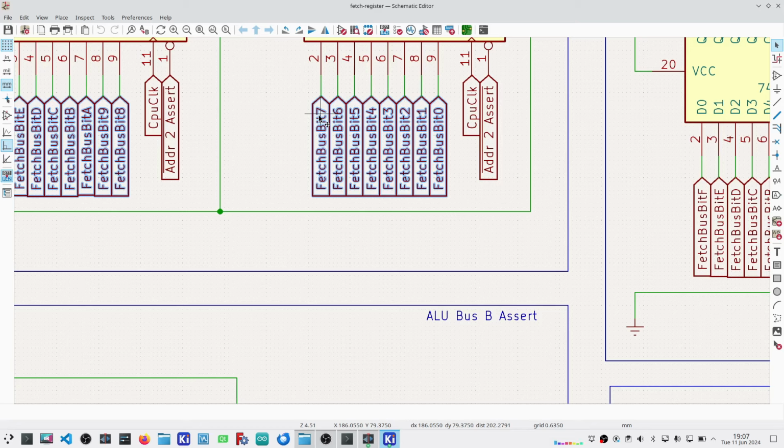It makes far more logical sense here to have it ordered the way I do in the schematic, and far more logical sense to have bit 0 refer to bit 0 in the emulator, not having those reversed. One is a naming association, that's in the emulator. One is a positional association, and that's here on the schematic and on the breadboard and ultimately on the PCB. So everything else turned out okay. So now it's just a matter of cleaning up the PCB design.